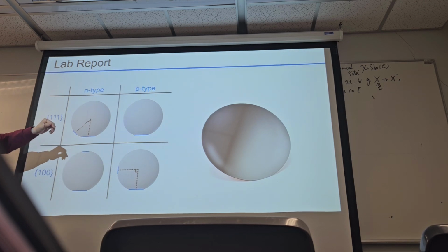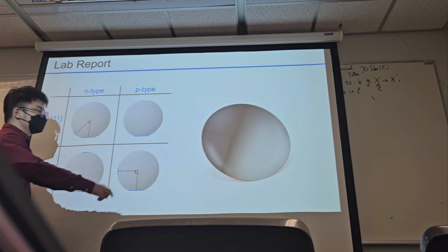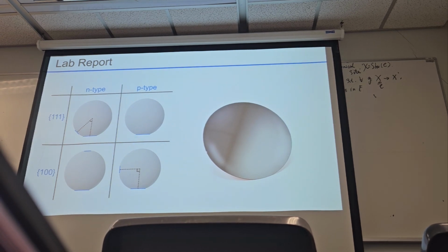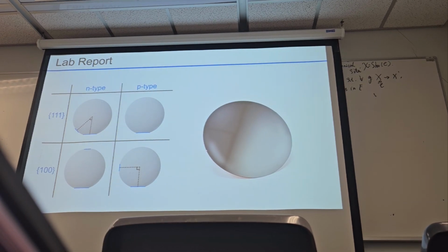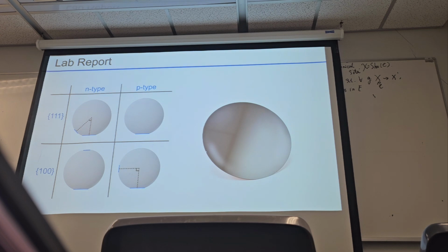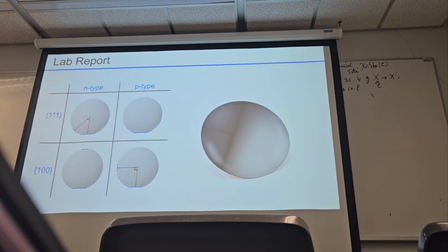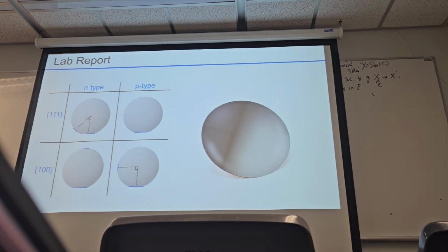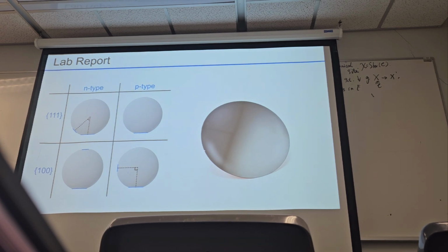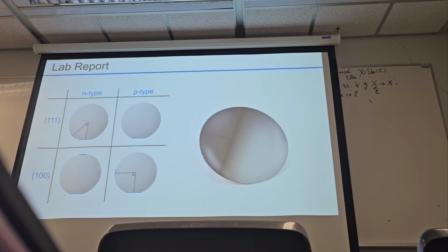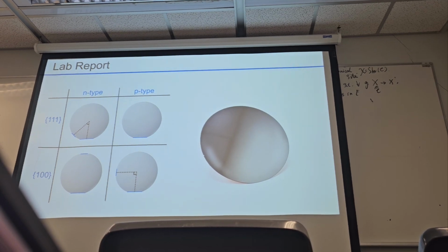So that's the reason why for wafers over 8 inches, we are using the notch, okay, first to tell us what kind of wafer it is, and second, this notch can tell the equipment to do the micro alignment. Okay, so during the lecture we saw some videos. You see the automatic transfer system, and they are using this notch to identify the orientation of the wafer.